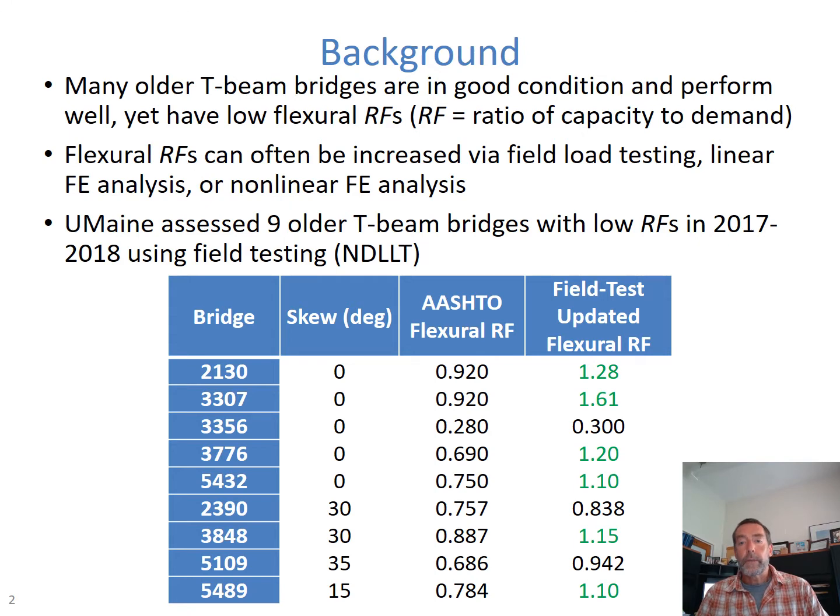DOTs are very interested in accurate rating factors, and when we compute them using conventional AASHTO provisions, we often get conservative values. We can increase them essentially in 3 ways. We can do field live load testing, linearly elastic finite element analysis, or nonlinear finite element analysis.